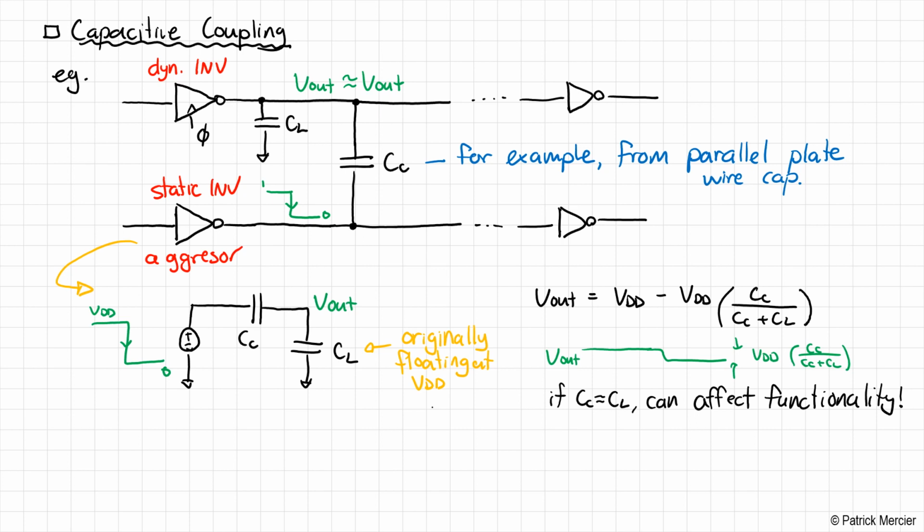All right, so therefore the conclusion here is that layout, particularly when we're talking about dynamic logic, although this applies to all other forms of logic, is very important. You really have to be careful about how you are doing your layout to make sure that you don't have any unnecessary parallel plate capacitance that might adversely affect your dynamic logic circuits. Okay, this is a very important point. Now, I do want to make a note.